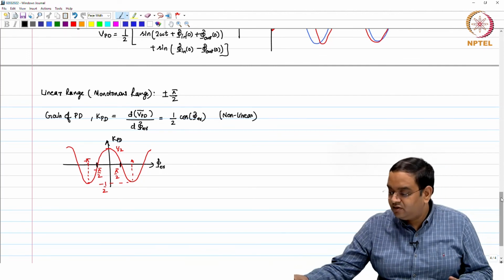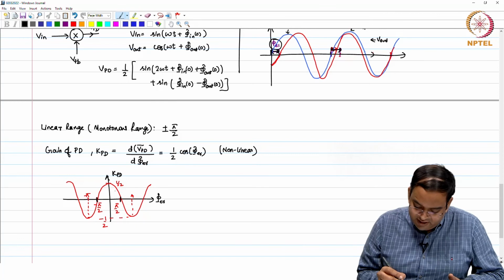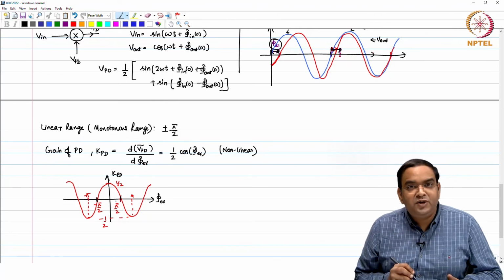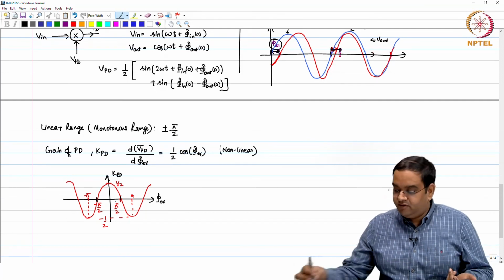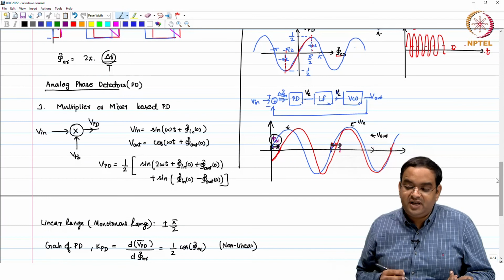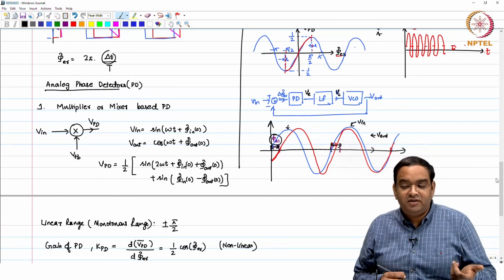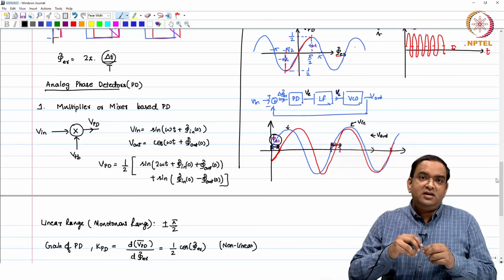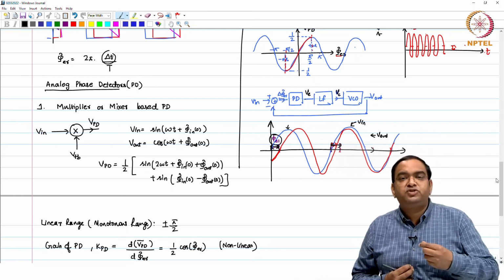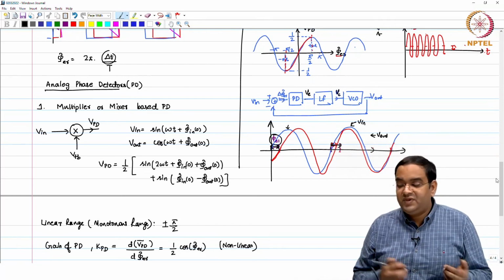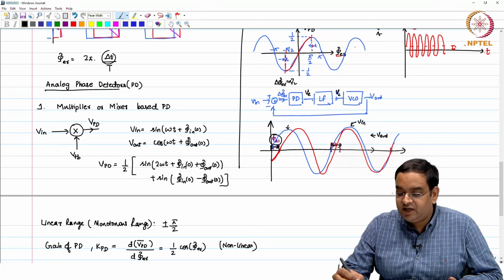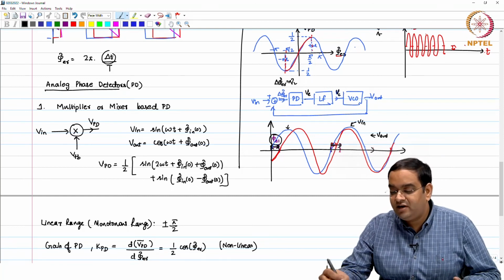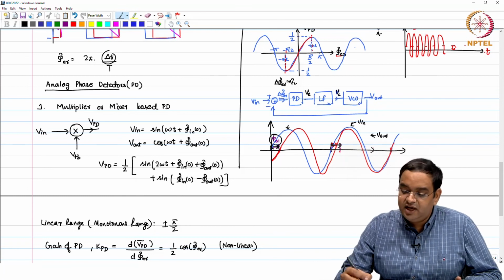What do I mean by dynamics of the PLL? Well, if your phase error is actually very close to pi by 2, the phase error detector output, we have seen here, is maximum, but in that case when you are applying the change it is going to be very small. To begin with, I have a phase error of pi by 2 here. So, with respect to pi by 2, I get V error half and all this frequency change, it comes back.